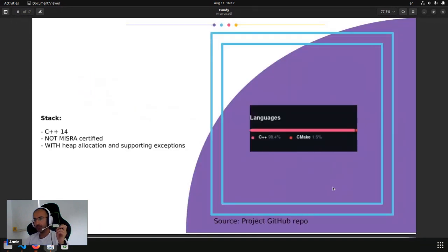Okay, let's go to the implementation. In several places you can find in the AUTOSAR project that it's based on C++14. At least by the time I was starting the development, the older version was based on C++11, and then later on they upgraded to C++14. In a real-world scenario, you cannot directly use C++14 to build an ECU using the adaptive AUTOSAR platform for the whole design of your ECU, because from an ASIL perspective, you need a certain amount of safety for running a system, and it also applies to your coding.